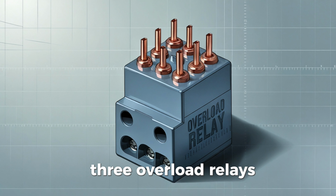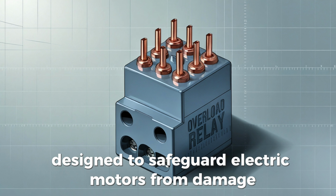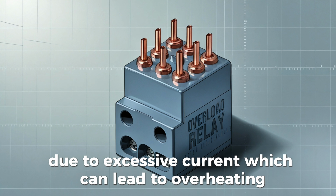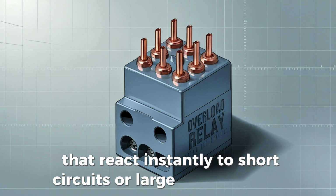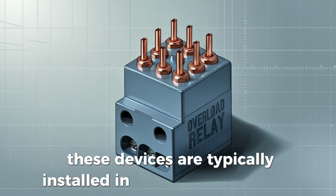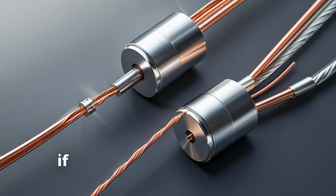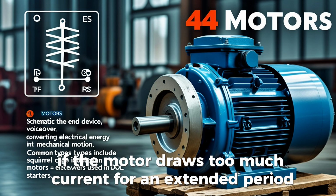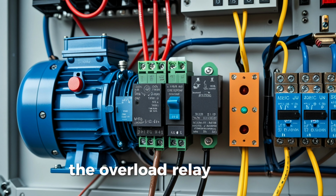3. Overload relays. Overload relays are protective devices designed to safeguard electric motors from damage due to excessive current, which can lead to overheating. Unlike fuses or circuit breakers that react instantly to short circuits or large current surges, overload relays respond to prolonged overcurrent conditions that are just slightly above the motor's rated capacity. These devices are typically installed in series with the motor and work by monitoring the current flowing through the motor conductors. If the motor draws too much current for an extended period, often due to mechanical overload, a jammed load, or low supply voltage, the overload relay will trip.